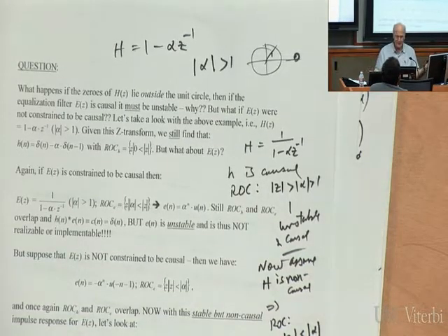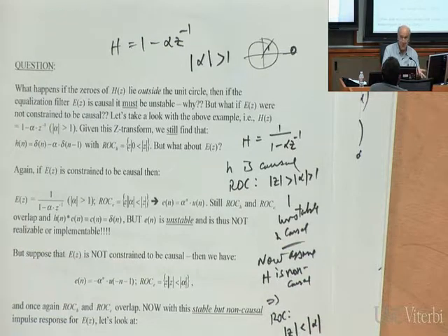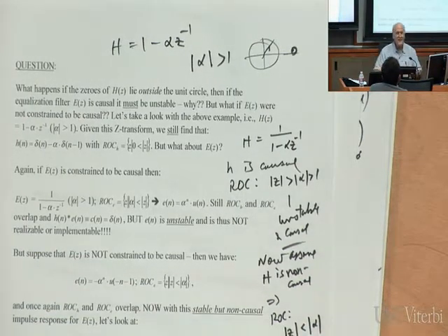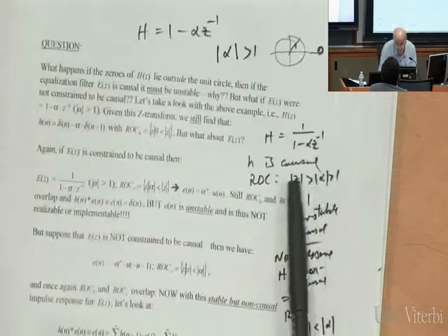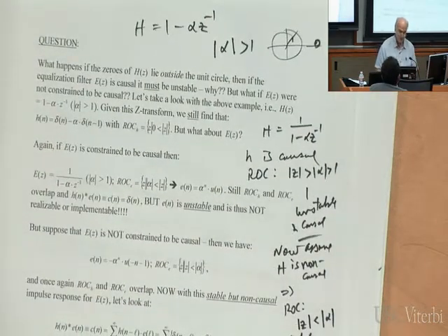What about that? By golly, the magnitude of alpha is greater than 1. The unit circle's there. So this is stable. Look at that. You heard that expression: you can't have your cake and eat it too. Well, this is a good case. You want it causal? It's not going to be stable. You want it stable? It's going to be non-causal.